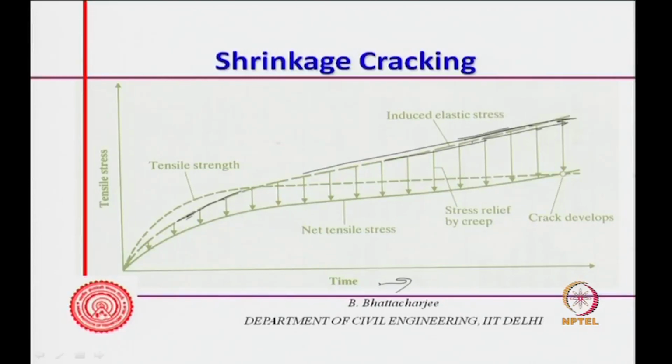Fortunately, there is some amount of relaxation because of creep, because you have a tensile stress which is sustained with time. So, there will be some relaxation due to the creep effect, because it is a restrained structure. Restrained structure shows shrinkage cracking.